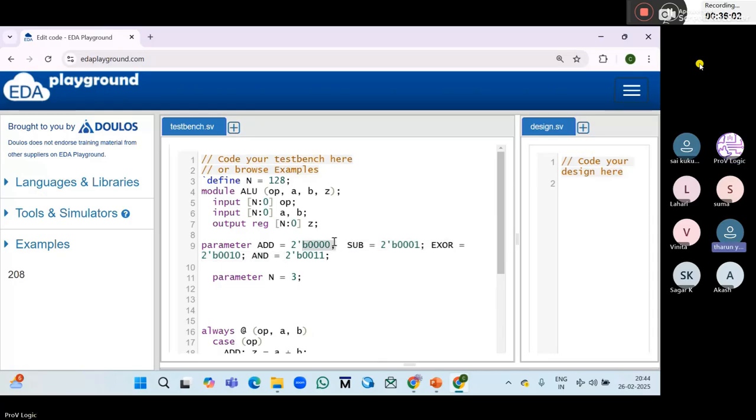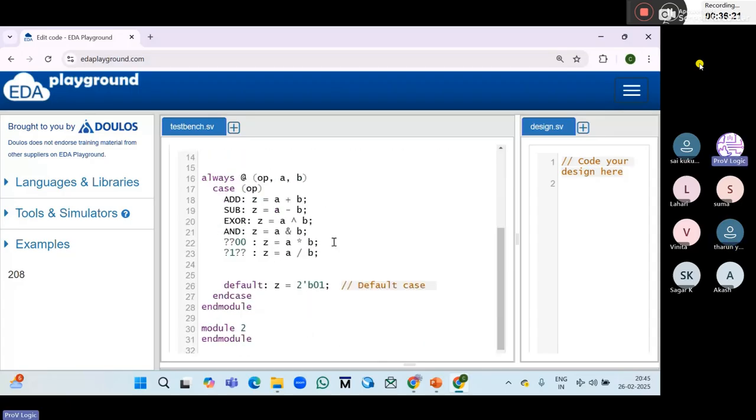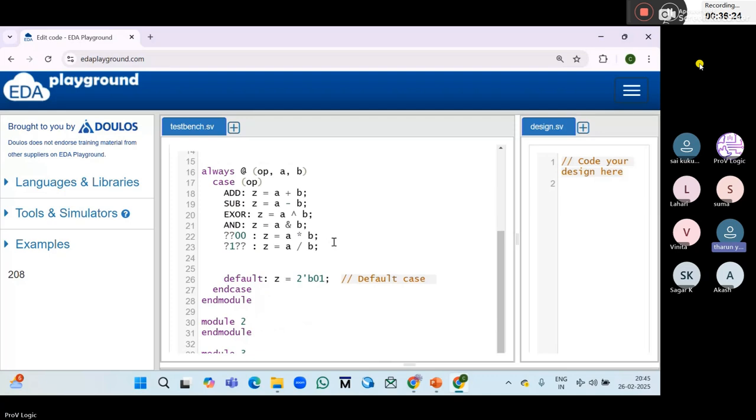If I want a 126-bit, actually here we declare 128, right? For 128, we have to give 8 bits size, right? Yes. So if I want to use a 126-bit size in the case statement, I need to put question marks for all the remaining bits. You need to check whether all those scenarios in that 128 bit have the same output.